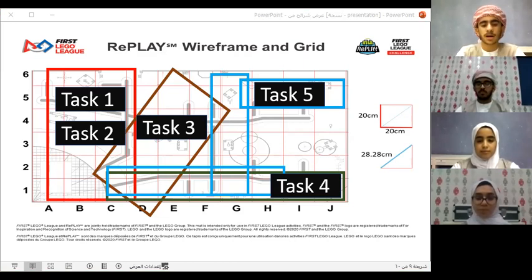During our task programming, we used sensors to ensure that the robot reached the target accurately. We used the light sensor to trace the black line and normalize it to correct the path of the robot. And by designing balanced parts on the robot's body, we ensured the tasks were executed with high accuracy, and we also used multitasking program segments that run at the same time to save time.